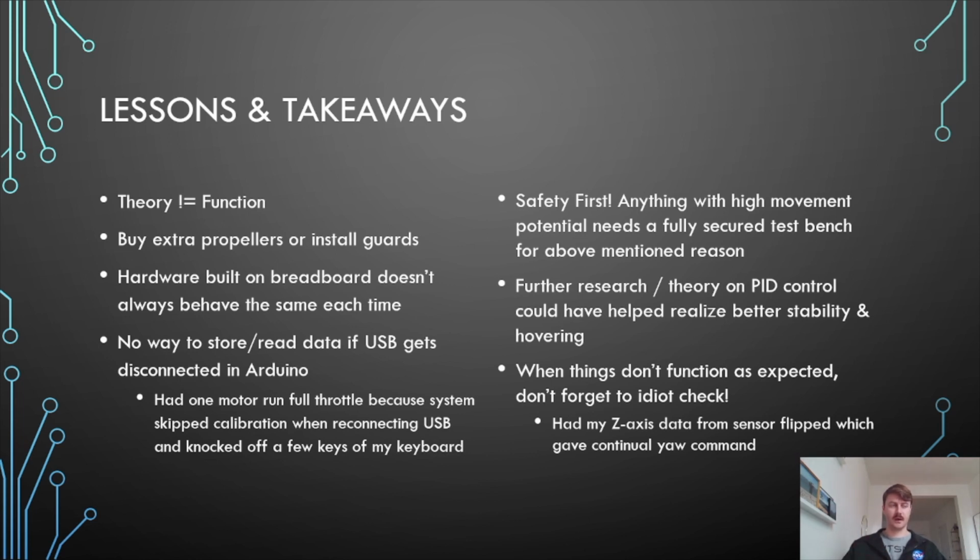One thing I learned in this project is that you can't reconnect an Arduino without it restarting the whole program. I tried at one point to get flight data. I set up variables to hold the flight data, and then I was going to reconnect it so I could do some data-driven design, import the flight data, and then improve the controller that way. Turns out it just restarted my program, and because the battery was still connected, it jumped over the calibration phase and started the propellers, and it just flipped over.